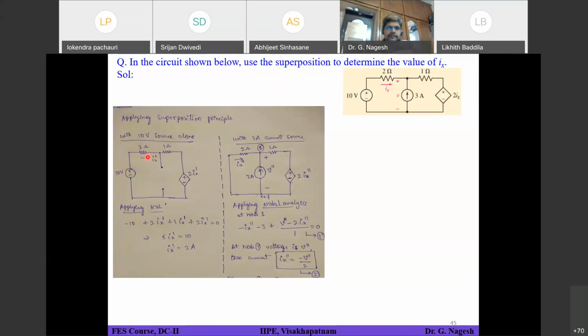Sir, that's from the independent source definition. An independent source itself states that whatever circuit you connect, my 10 volts remains the same. That's what an independent source states. 10 volt will be the same, but current across it may not be the same, because current will depend on resistance and everything, the circuit parameters. That's why it has changed. Okay, sir. Thank you, sir.